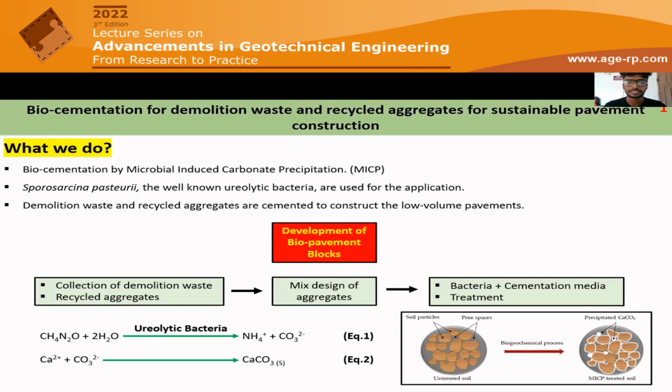We are following the saturated treatment condition, and we injected the bacteria solution from the top of the sample mold and left it for 2 hours. Then we drained the bacteria solution from the mold, injected the cementation solution, and kept it for 24 hours. We replace the fresh cementation solution day by day, and we continue the treatment in a similar manner. I want to mention that we also provide nutrient growth medium with the cementation solution for efficient bacterial activity.